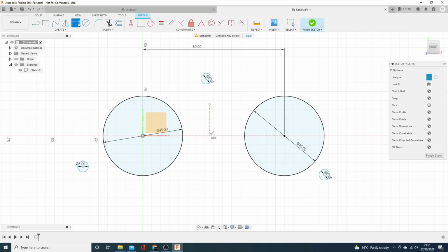And let's also, for reasons you'll see later, make it 13 millimeters long, because that's the height I need this off. And then let's also make it 40 millimeters from the edge there, because that's the center between these 2 points. Then that means I can make that coincident to there. So that's now all constrained.